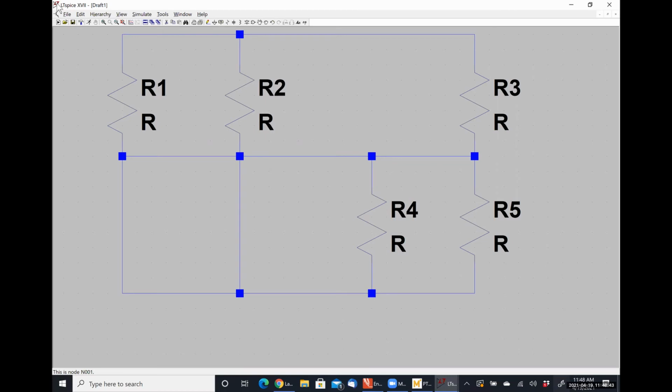So that's how I can use LTSpice to confirm whether or not I have the correct magnitude: I'm just going to match peak values, and then the phase response I can get using this expression right here. So I can't look at it directly per se, but I can get it from here to check that things are correct.